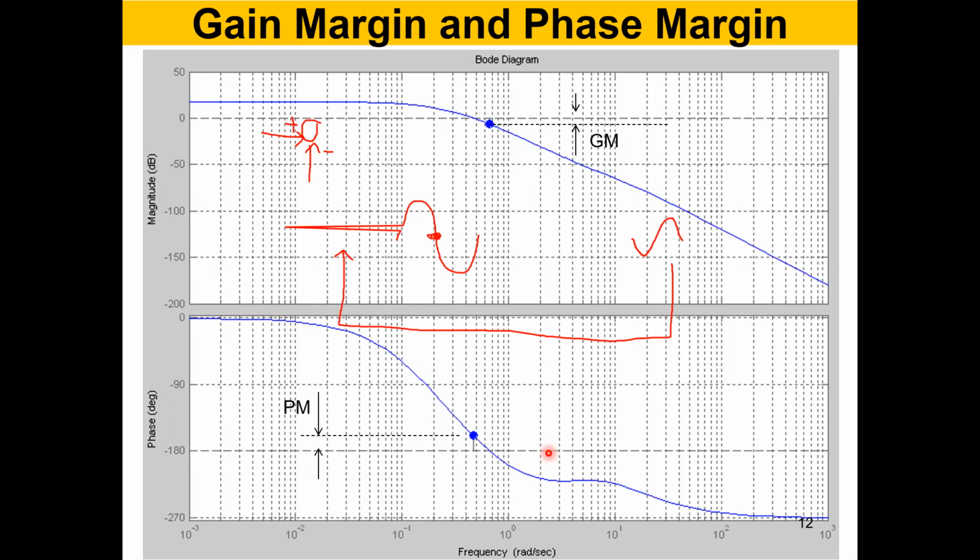So this gain margin and phase margin give you some insight into the plant, okay, where you are qualitatively with respect to the plant. You need to use gain margin and phase margin, right? Keep additional phase margin and gain margin in your plant. Getting too close, having narrow gain margin and narrow phase margin, it's not good.